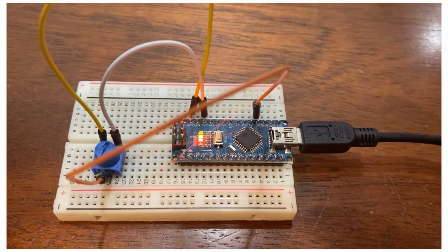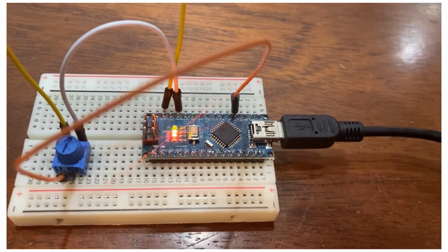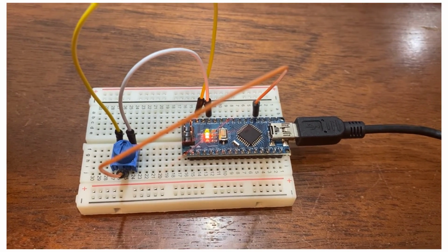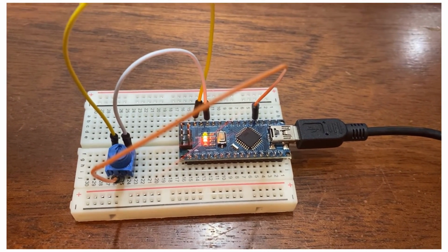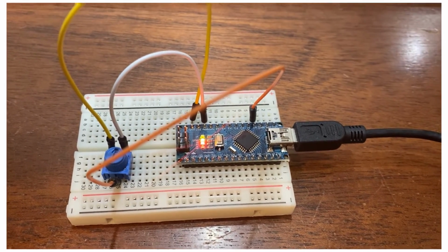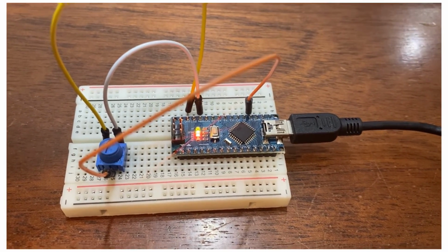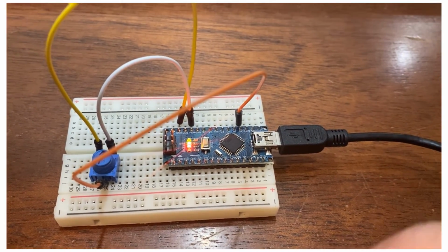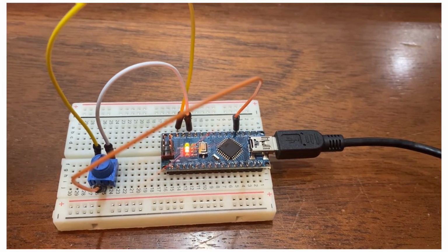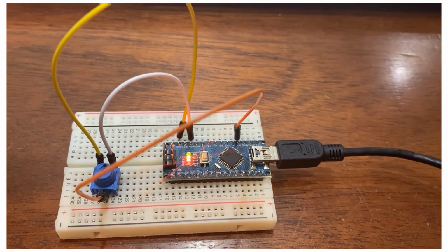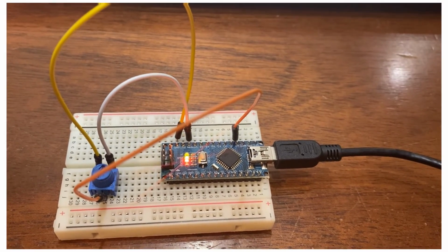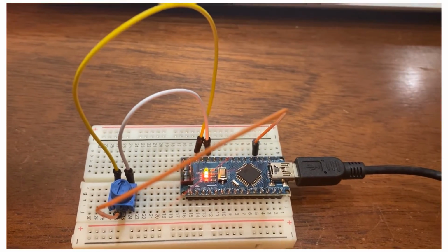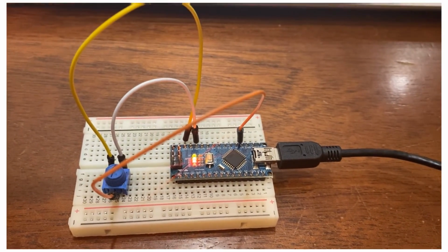Here we have the setup for the Arduino part 2C. Similar to part 2B and part 2A, actually nothing has changed on the breadboard. The only thing that has changed is the way that we're going to get our results. Last time we mathematically scaled our results down to a range that we wanted between 0 and 5 and used the float function to get our results into decimals. This time we're going to let the Arduino program automatically scale down to our desired scale using the map function. And those results can be seen numerically and graphically.